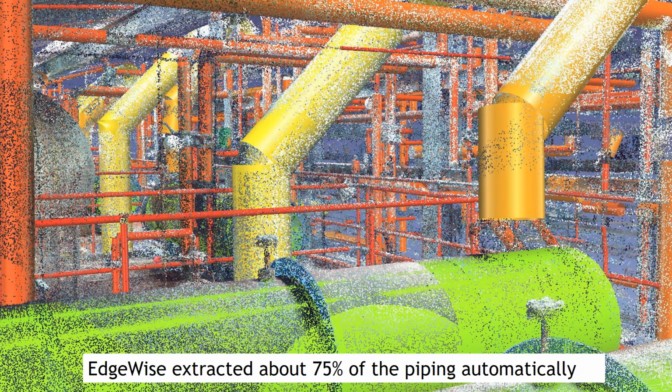Now, one of the things, and I'm sure I'm stepping on some feet here, that you need to bear in mind with Edgewise is that it's not a pipework extraction software, it's a cylinder extraction software. And the reason I say that is that roughly in the middle of this image, you can see it's picked up all the handrails, because let's face it, there's nothing different between a pipe and a handrail. They're all cylinders. So that is one of the things that Edgewise does pick up on.